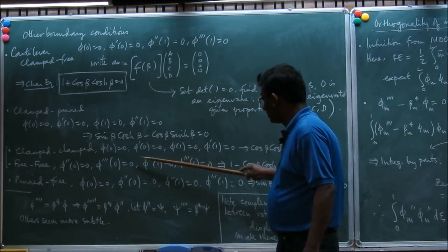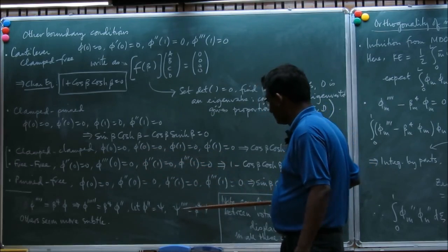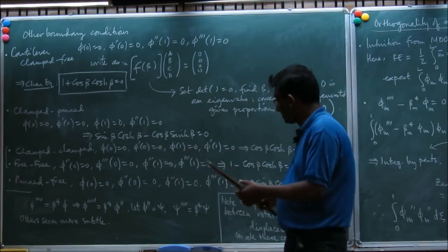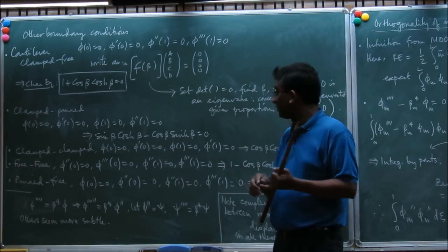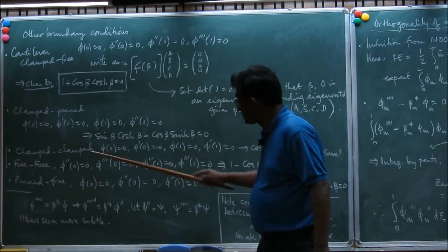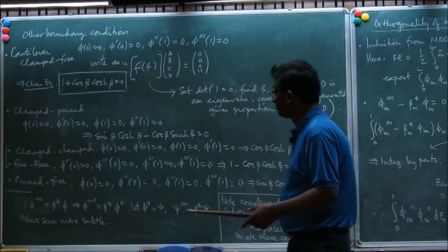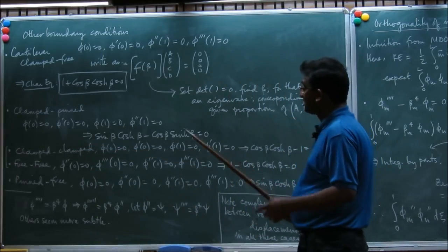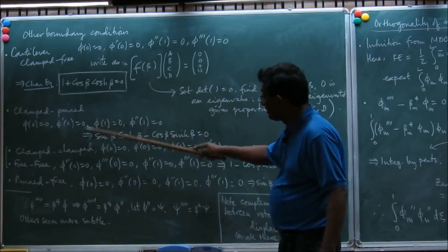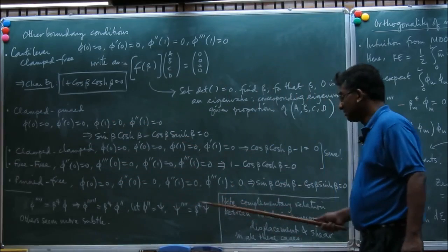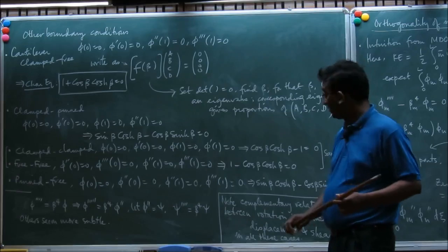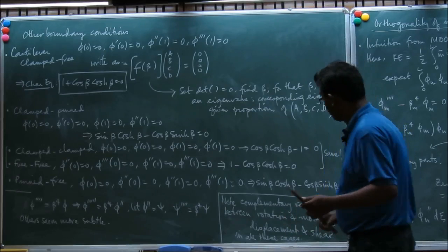And so the way it works out is that the betas are the same because the governing equation is the same and the boundary conditions are the same. So there is this intuitive way to see why the clamped and the free have the same natural frequencies. Why the clamped pinned and the pinned free have the same natural frequency seems more subtle. I don't have a simple intuition for it.